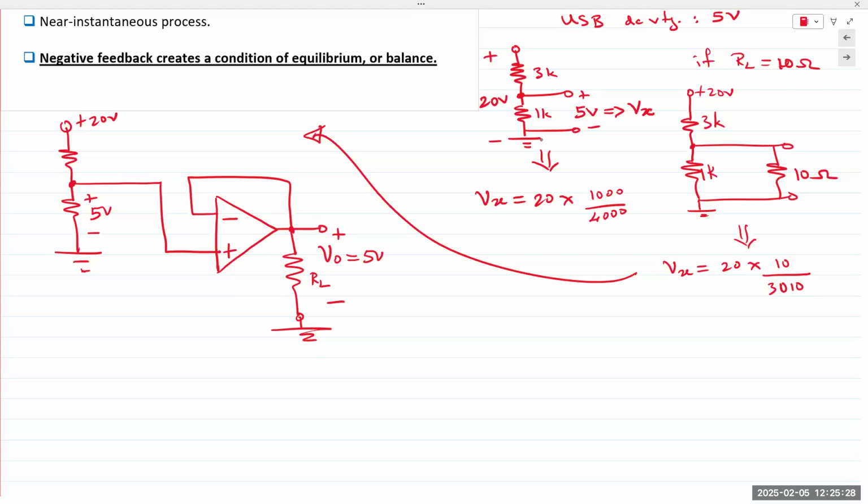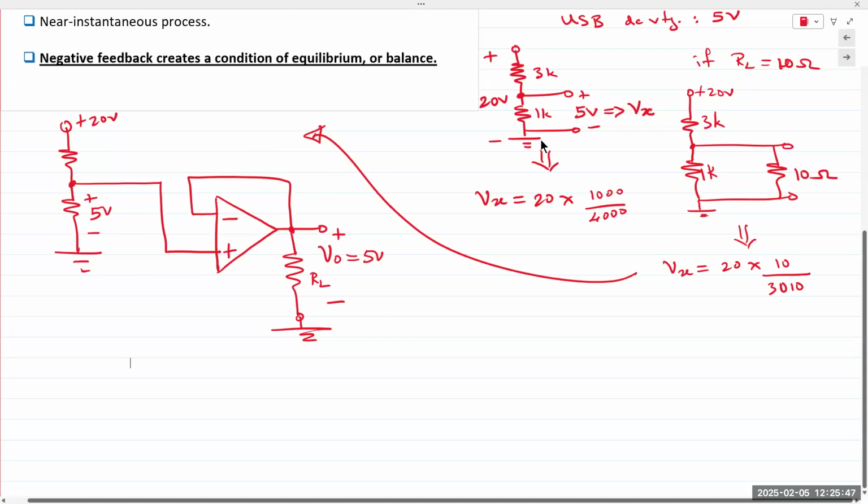An op-amp has the property of very high input impedance and very low output impedance. And because it has low output impedance, the output voltage would not change and remains constant. If you apply 5 volts to this circuit, you would receive 5 volts at the output. And you can try that in the lab. So this is the first circuit, just an explanation for one of the most popular applications of an op-amp.